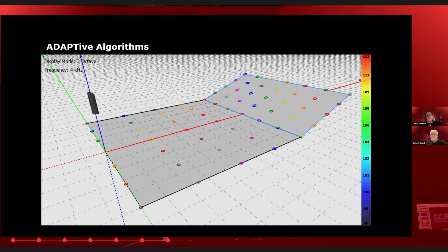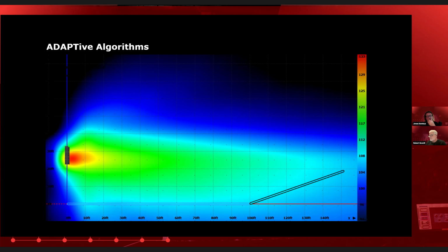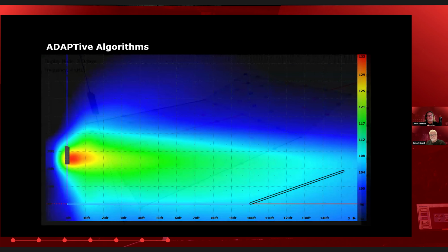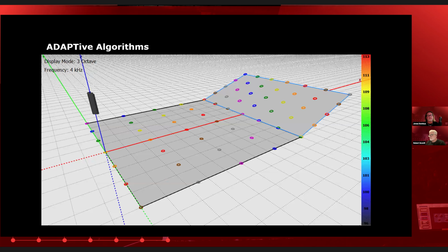Then on top of that, not only are we creating in software the directivity shape and an even SPL polar shape to match the target, we also analyze the overall target frequency response, with a built-in target curve that we're trying to achieve.